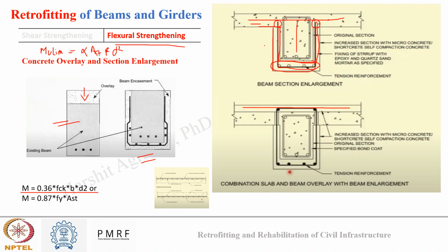But sir, generally we talk about having this complete in a square shape with an angle of 135 degrees. Maybe here they have not depicted that angle properly. They just wanted to show that the encasement is done. Here also some bending will be done to ensure that the stirrups are properly interlocked with the old concrete.